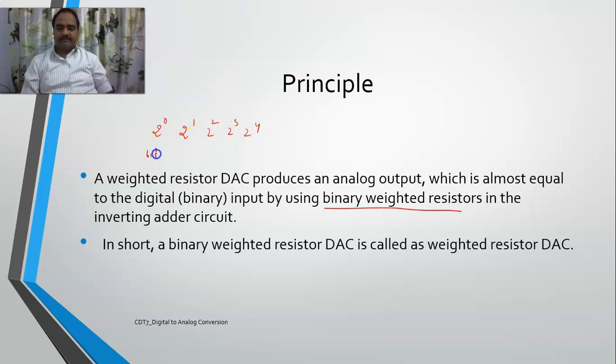This is the MSB, this is the LSB. If it is an n-bit device, each bit is multiplied by this value, so the higher the number of bits in your digital input, the more resistors are required.